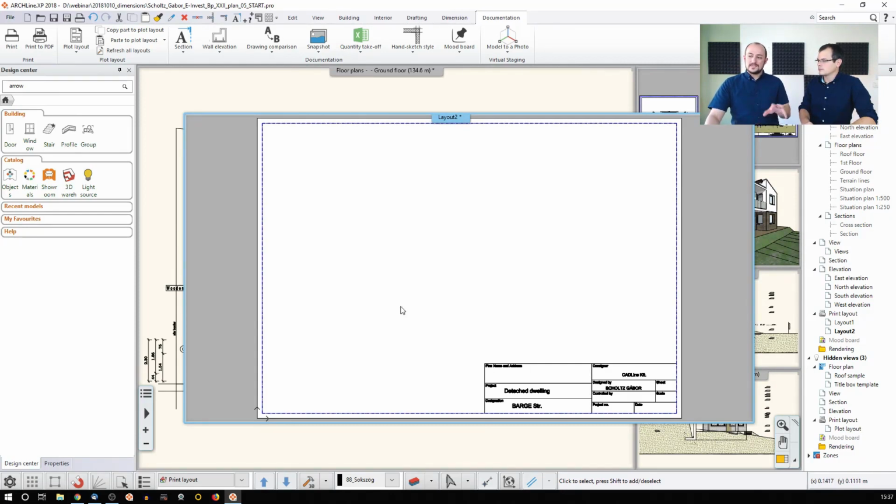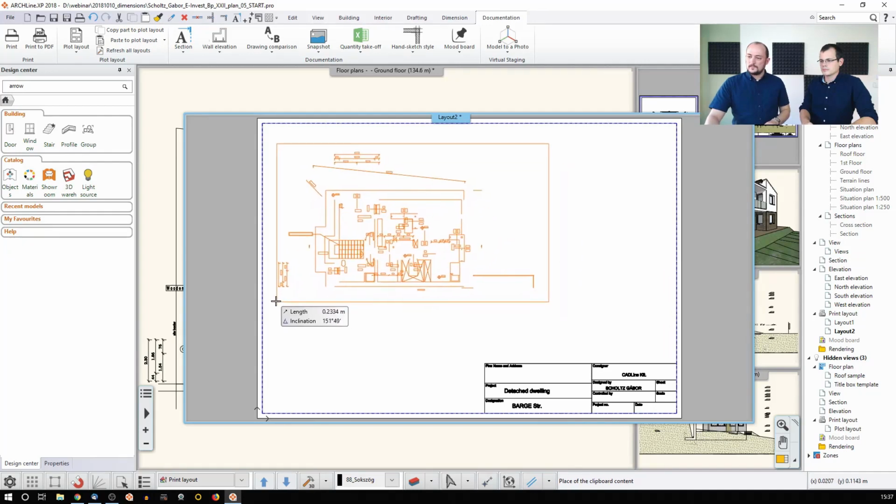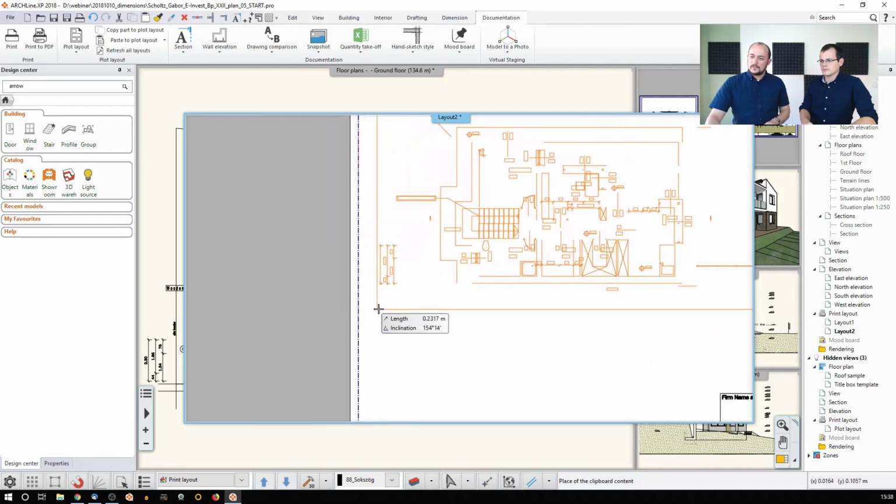And then now to assemble the layout, you can go and select, let's just go with the floor plan, and I should go with the ground floor. This ground floor should fall here in a size, I don't know, let's go with 1:100. I think this should fit the screen. And let's just place it over here.